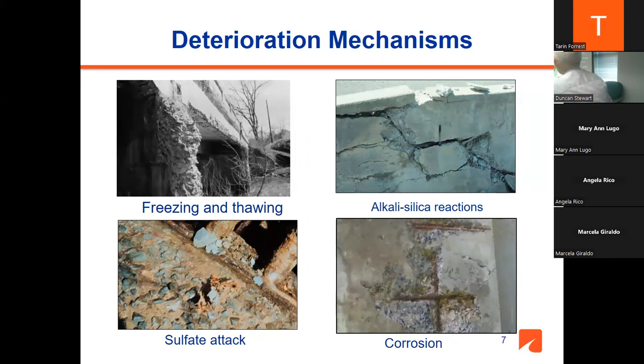And the reason is that water expands 9% upon freezing. So that's an issue for us. Same thing happens if concrete gets saturated, and if freezing takes place, there will be very high hydraulic pressures occurring, and that may break the concrete. So what do we do? We entrain small bubbles in the concrete.